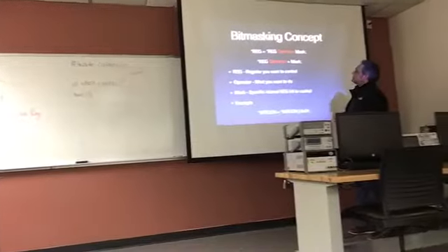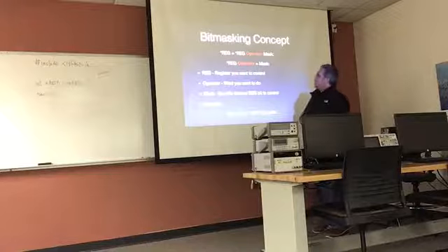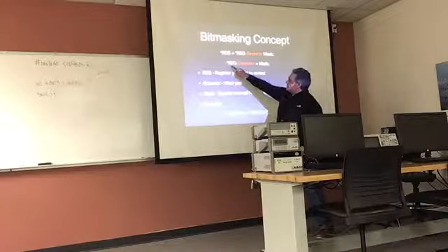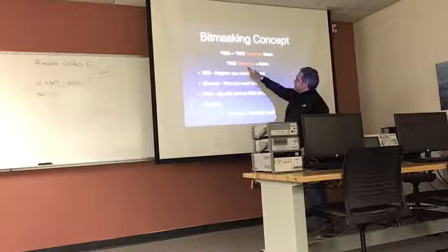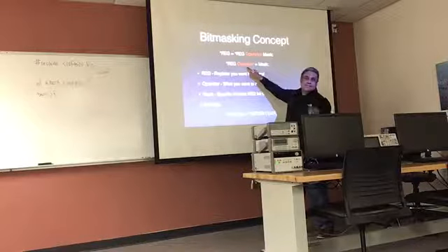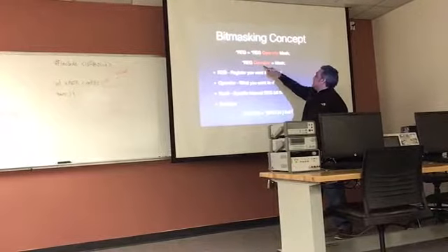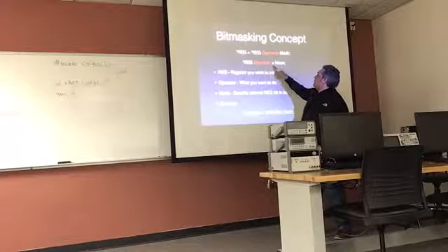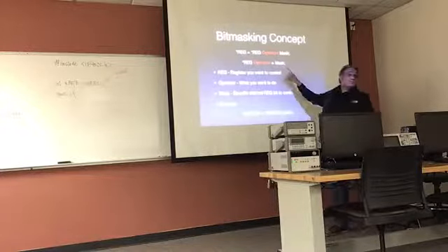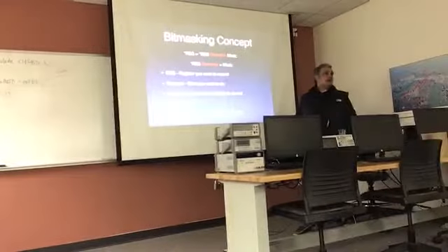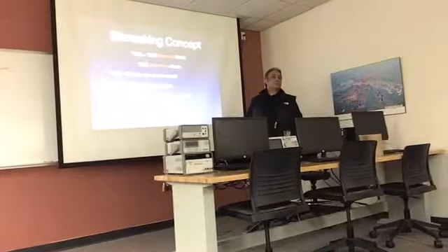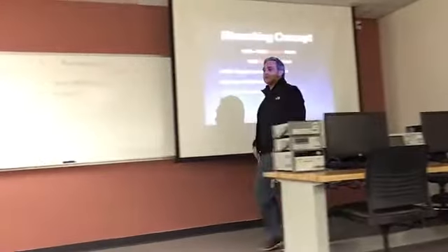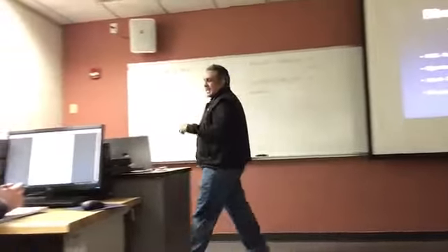So, here's how the shorthand works. You have the register, what you want to do, the operator, meaning like the gate, the set, the reset, the toggle, or the read. Well, the read doesn't work this way, but the set, the reset, and the toggle, equal, and the mask. These two instructions are exactly the same.